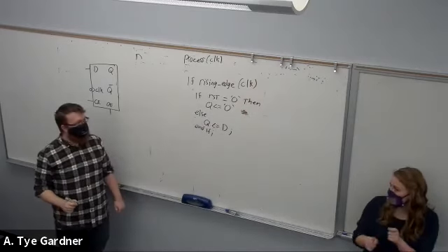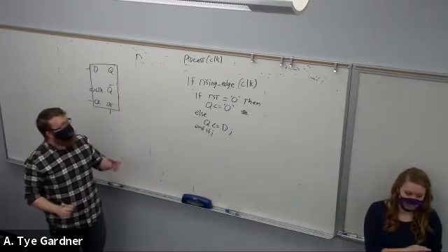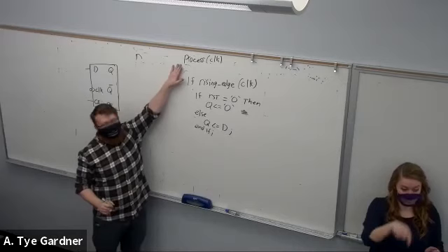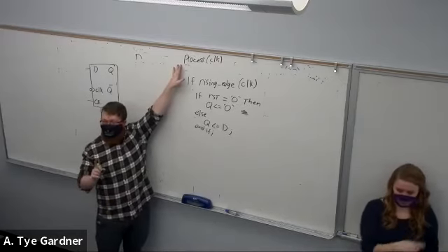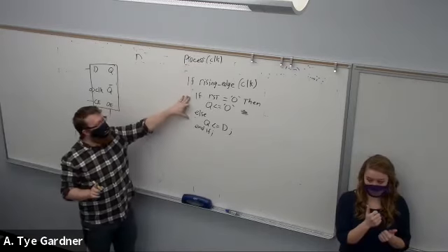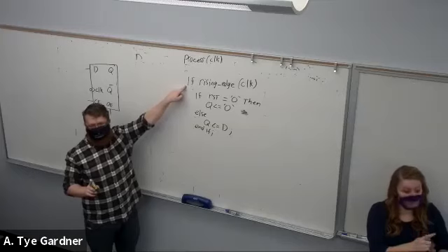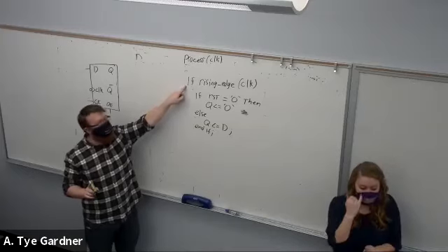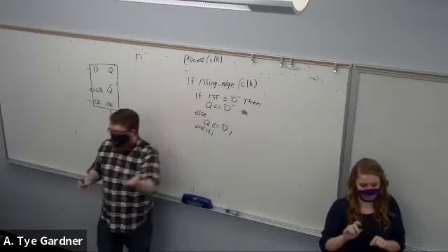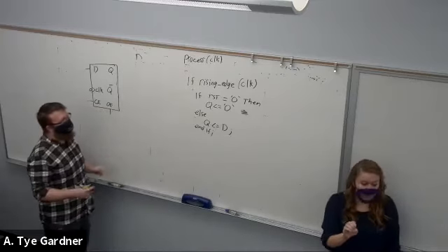Because previously it was changing anytime it went 0 to 1 or 1 to 0. Correct. So now the first thing that happens when this process executes: it's going to execute every time that the clock changes, but it's only going to update Q if it's a rising edge. And all I have to do is write rising_edge. You can also do falling_edge. Both of those are valid, they both work.